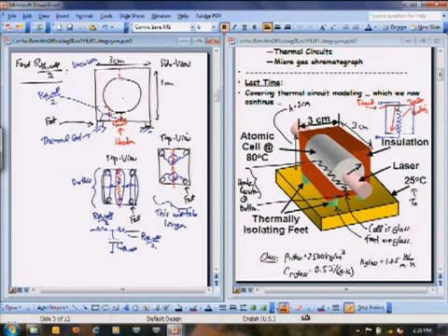If you're thinking of current, this is like current going into an open circuit. Right, so for heat, that's basically an open circuit. Okay, we see vacuum going up there. So the heat doesn't want to go up that direction, right? It wants to go this direction toward the foot. Okay, just like any circuit. So you really have to put your mindset into a circuit mindset. If you were calculating resistance from this point to that point, you would not include squares going up here. You can if you want. They're going to have a very small percentage change to your answer. They will change your answer. They'll change it a little bit. Okay, but it's not going to matter that much.